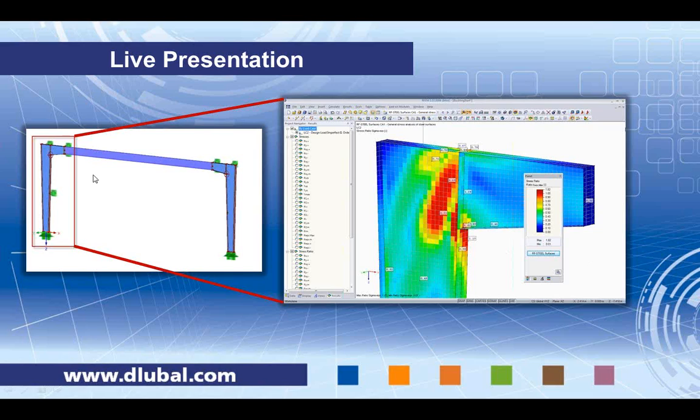In general, you will not find an analytical solution for checking against local buckling of such parts where the bending moment has to be introduced over a corner of a frame into the column. Analytical formulas for plate buckling are available, to my knowledge, only for rectangular plates.